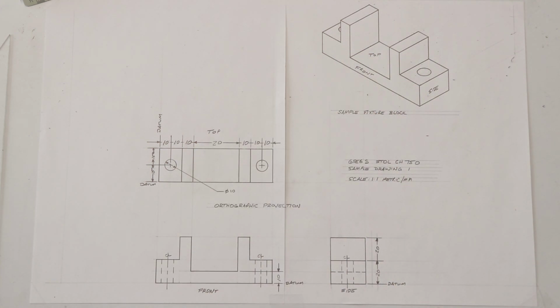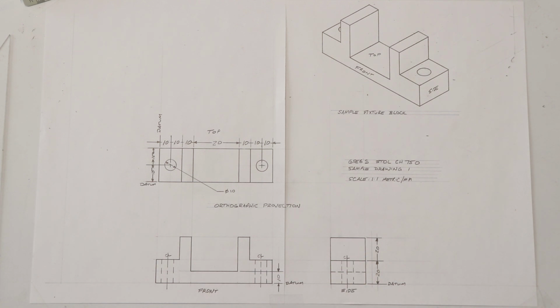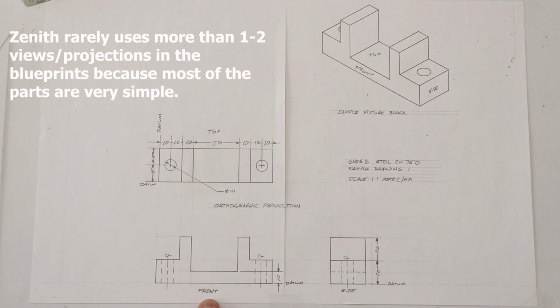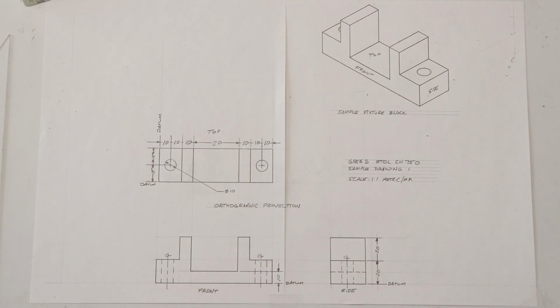If we were going to do an engineering exercise on this particular part, or a drafting exercise, normally you would take an isometric view of it, and then you would draw at least 3 sides of it in orthographic projection. So down here I've got the very front face of this part. If you were staring directly at the front of it and you couldn't see the sides and it wasn't rotated in any way, this gives you what you would see, and then a few dotted lines that show hidden features, and in this case those are simply the bolt holes.